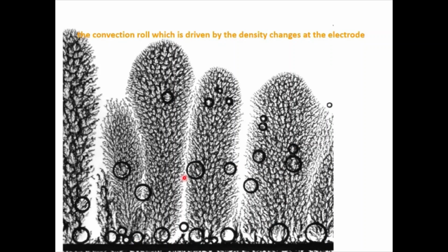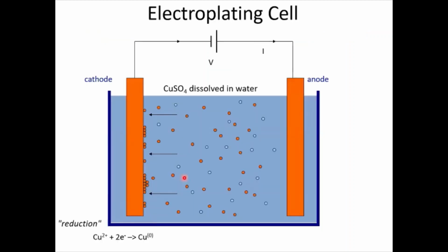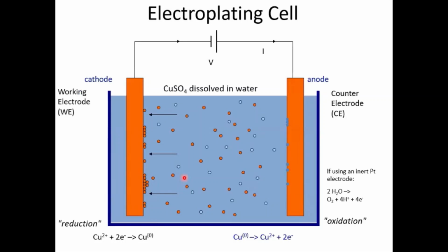Near two electrode geometry. So this is one of the conventional ways. For three electrode geometry, you prepare again any nanostructure using this. So you have a bath, an electrolytic bath. You have an anode and a cathode connected to the power supply. For a simple example, again I try to explain with copper. You have copper sulfate as an electrolyte. Just apply current or voltage in between the electrodes, and usually it will have a three electrode geometry.